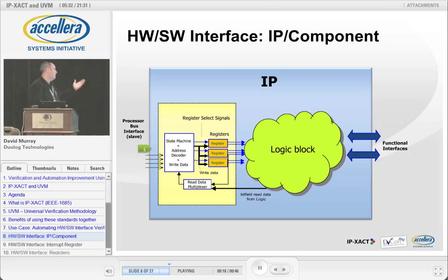Again, it could be AXI, OCP, APB, etc. There is a protocol decoder here, extracting the address information, and then there's a set of registers that information is written into, and these bit fields are actually communicating with a logic block. Also, there's status information coming back, or information from the registers also coming back, so you can have both write and read operations.